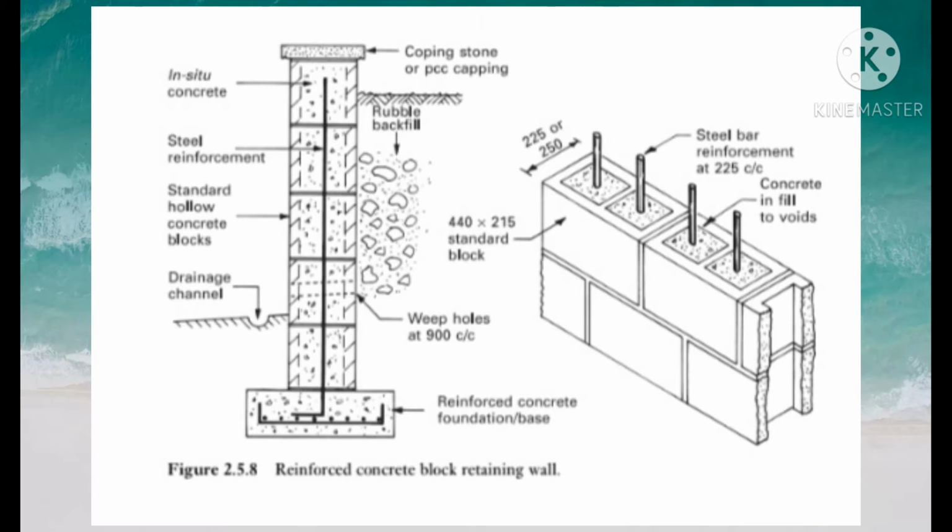This figure shows the application of standard profile, hollow, dense, concrete blocks laid in stretcher bond as permanent formwork to continuous vertical columns. The height potential and slenderness ratio, or effective height to width, for reinforced masonry walls can be enhanced by post-tensioning the structure.